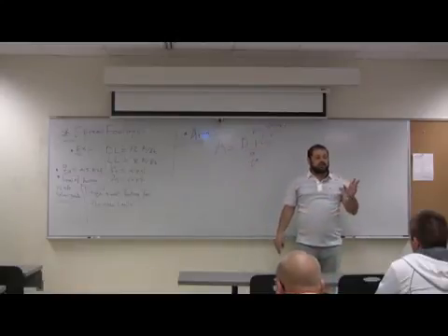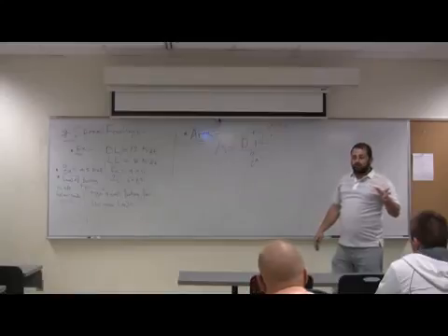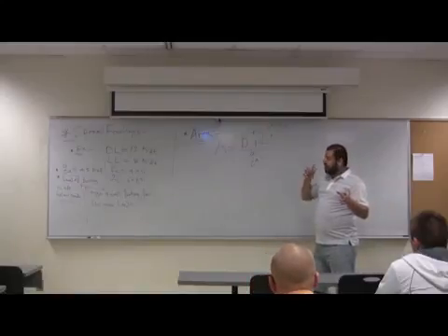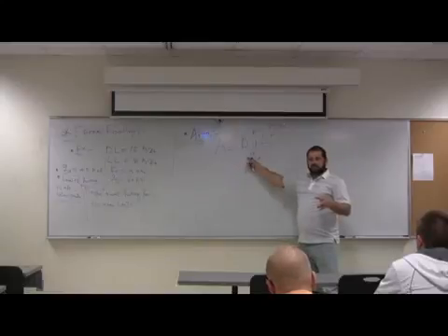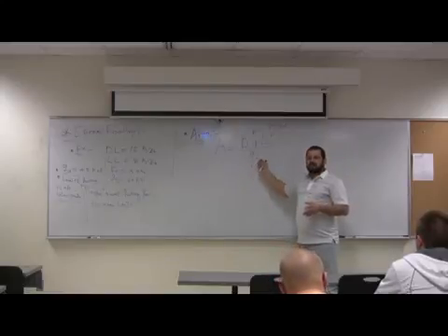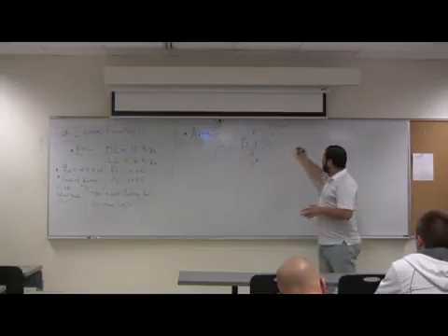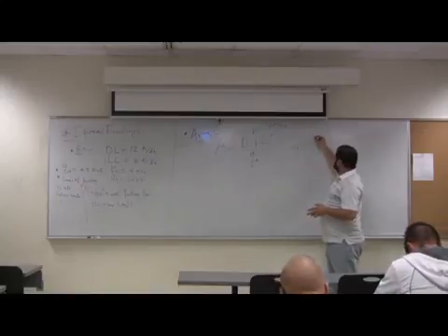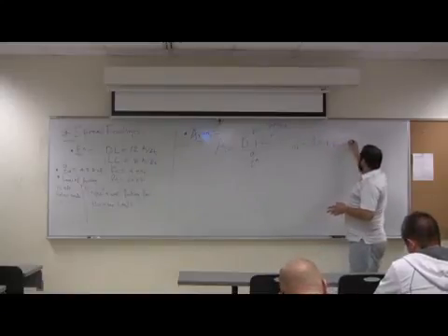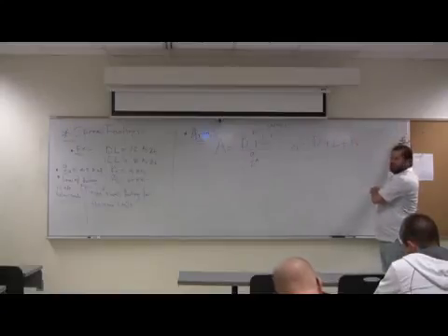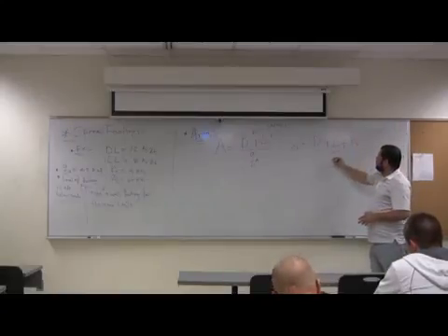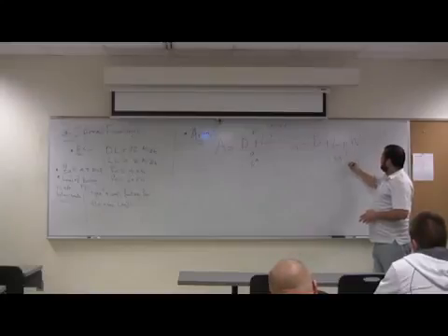Sometimes if you have lateral load like earthquake or wind load, the ACI code allows you to increase this one too by 33%. It allows you to increase this one by 33%. Or D plus L plus wind or D plus L plus E earthquake divided by 1.33 Q allowable.